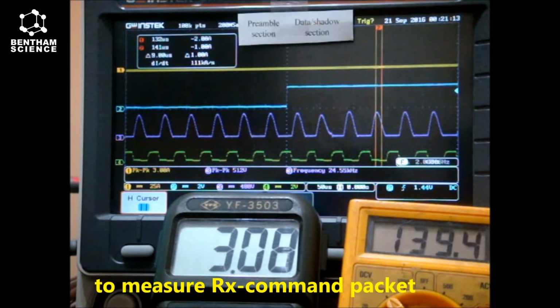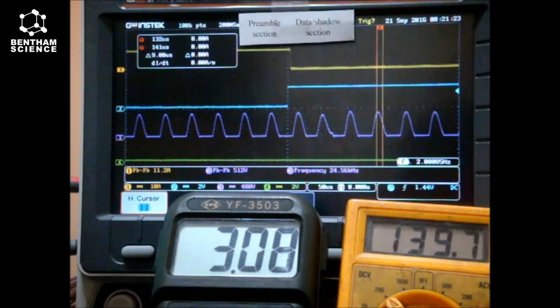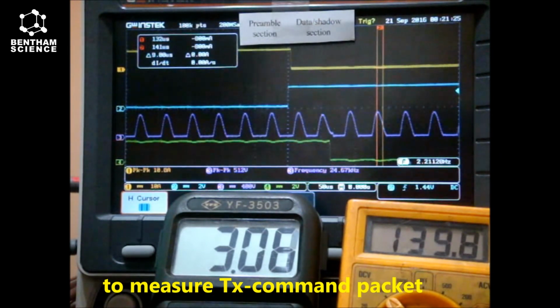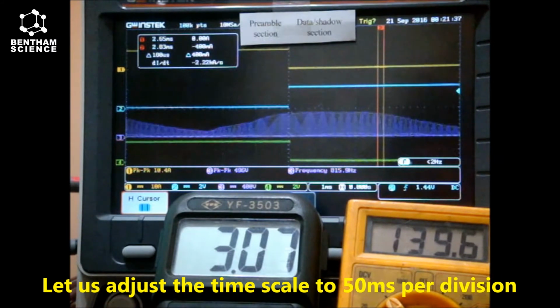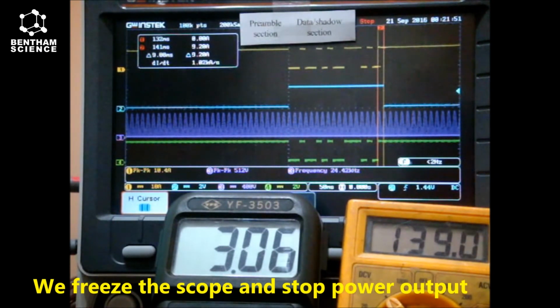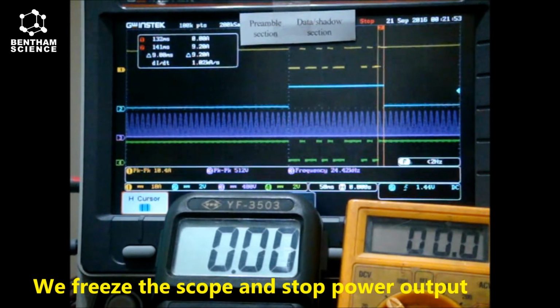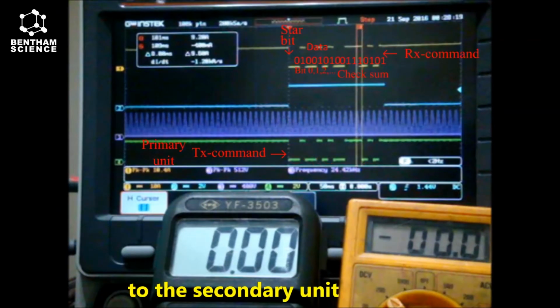We change channel 1 to measure the RS command packet, and change channel 4 to measure the TX command packet. Let us adjust the time scale to 50 milliseconds per division. We freeze the scope and stop power output. The primary unit sends a command packet to the secondary unit.